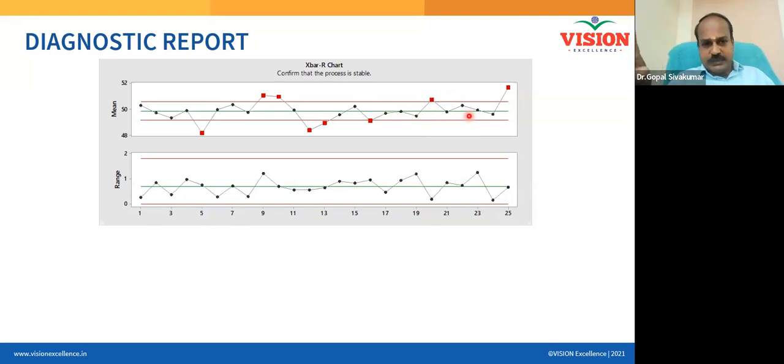So when you do such things, please at least add on some assumptions. What are the assumptions? The study is conducted over such-and-such period, and data is collected in subgroups with a subgroup size of 10, over a period of a week, and the process is assumed to be under statistical control. If you include all of this, whatever you have written is correct. You are passing on realistic information to the other person. If you don't write the assumption, you are actually passing on false information.